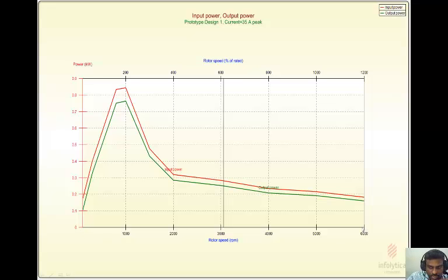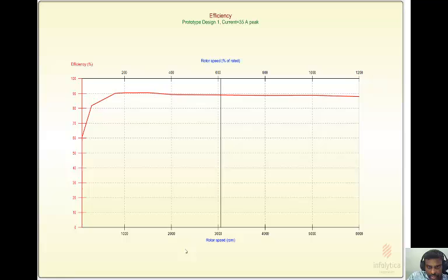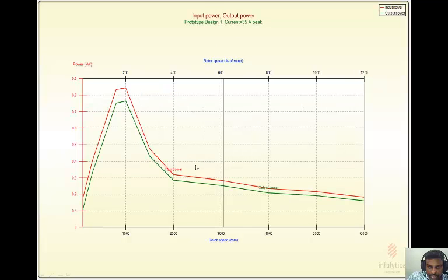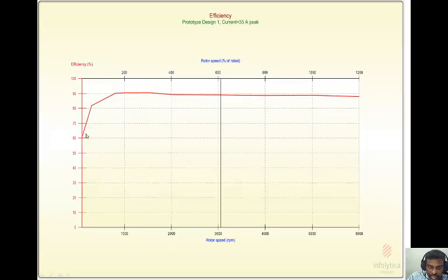If your vehicle operates at 6000 rpm, you can easily calculate the efficiency at each and every point. Based on this we calculate the efficiency, and at 500 rpm it comes around 84-85 percent, at 1000 rpm it reaches 90 percent, and at 6000 rpm it delivers 89% efficiency. So the idea behind this design is we want to design an 85% efficient machine at the rated speed.